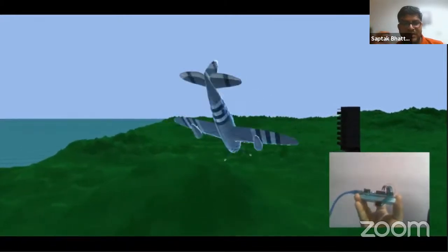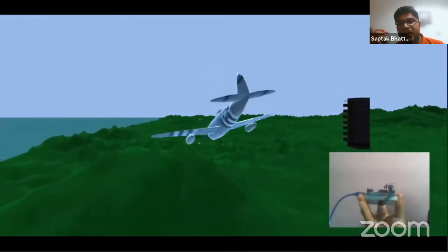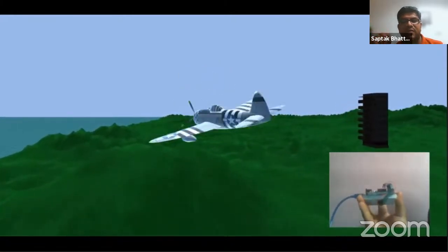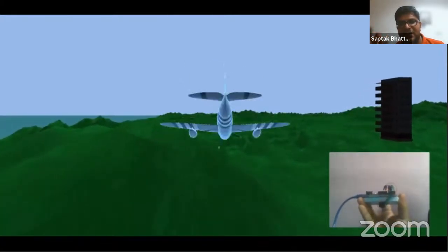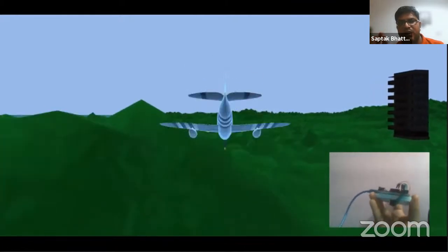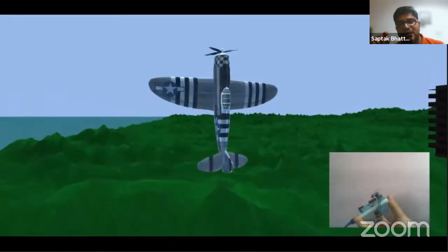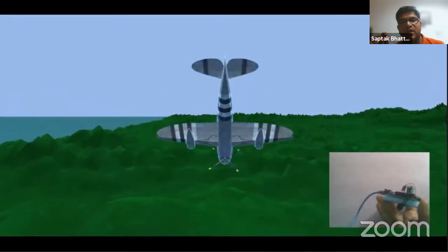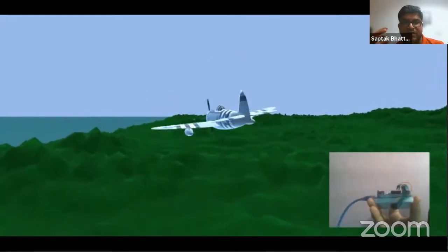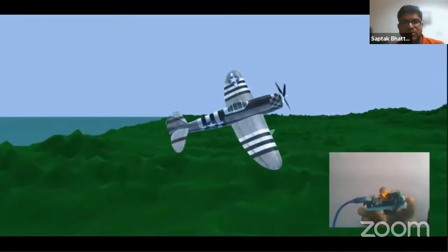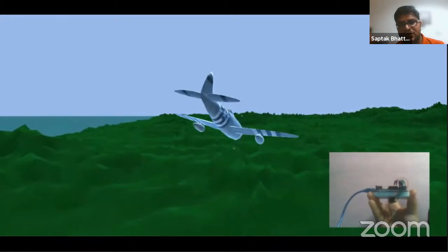Now the program or the script in Unity 3D basically takes those acceleration values in the range of -1g to +1g through the designated communication port, and then converts those x-axis, y-axis, and z-axis acceleration values into corresponding roll, pitch, and yaw, and then it assigns those values to the game object so that the orientation of the game object can be controlled.